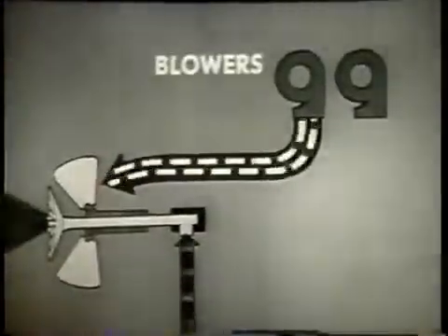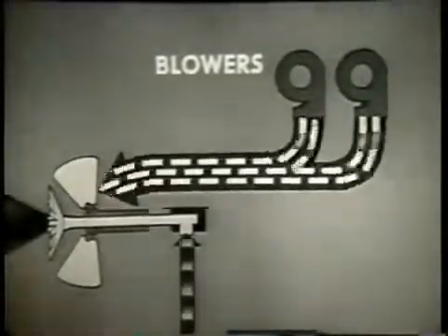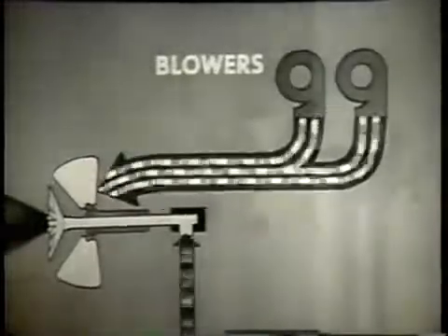To control the amount of air entering the furnace, you vary the speed and number of the forced draft blowers. In the return flow burner, you vary the pressure on the return oil line to control the amount of oil entering the furnace.